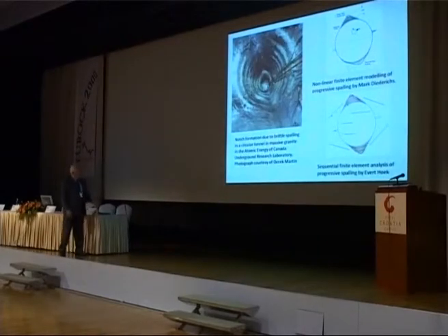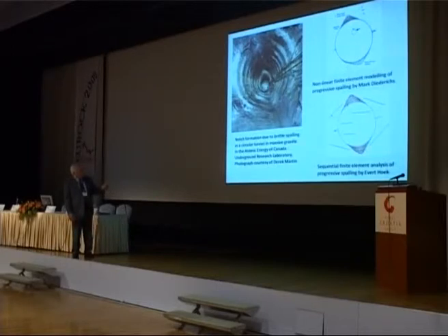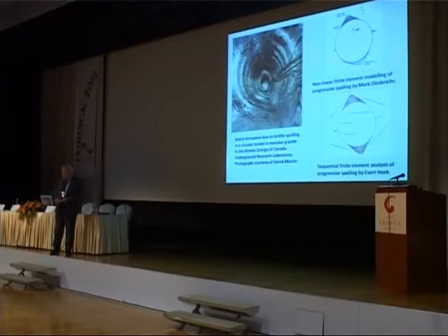This is from the Atomic Energy of Canada site, where you had quite deep spalling around the tunnels in granite. And here is an attempt to model this numerically by Professor Mark Diedrichs. The depth of the spall and the lateral extent of the spall is fairly well captured, but very poor representation of the volumetric changes that occur during spalling.